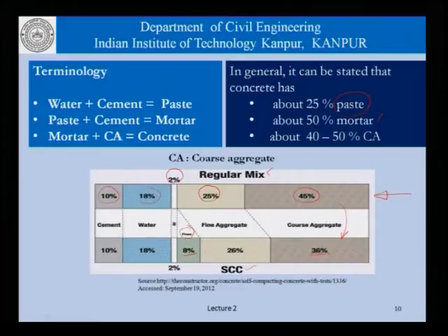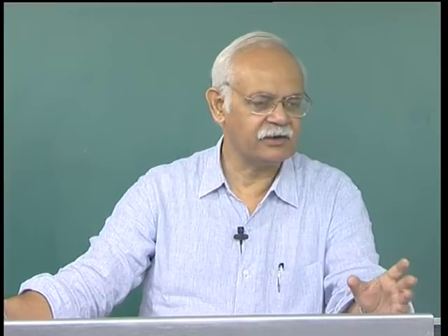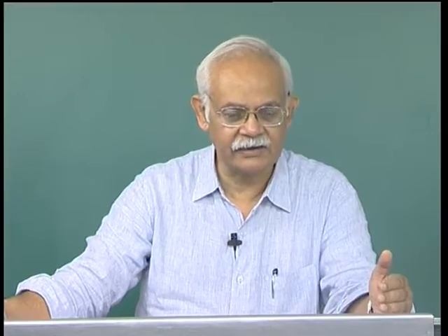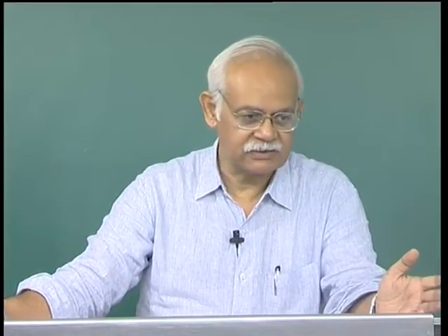So, we must understand, and this is the answer to the question in one of the previous slides, as to whether there is a need to change our definitions of paste and mortar, because paste is not only a mixture of cement and water in that sense, and any particles which are added to the concrete which have the same fineness as cement can qualify to be paste.